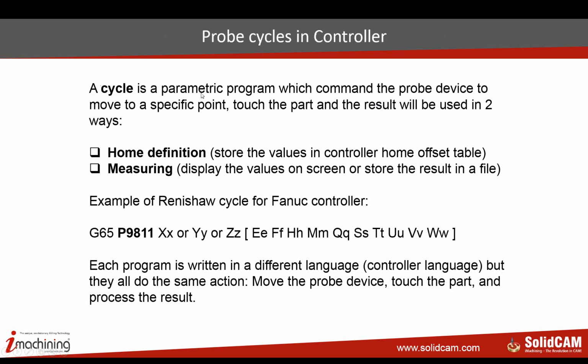We all the time talk about cycles. What is a cycle? A cycle is a macro program, a parametric program written by a machine manufacturer himself, or by a probe device manufacturer, because we have different controllers with built-in cycles, and we have controllers without built-in cycles.